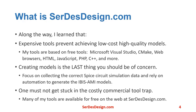My tools are based on free tools: Microsoft Visual Studio, CMake, web browsers, HTML, and more. I learned that creating an IBIS-AMI model should be the last thing you concern yourself with when it comes to creating IBIS-AMI models. Focus on collecting the correct SPICE circuit simulation data or hardware measurement data, and use automation. My tools rely on automation to generate models from measured and simulated data.